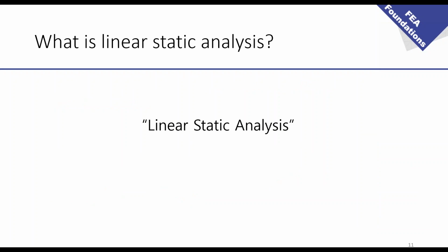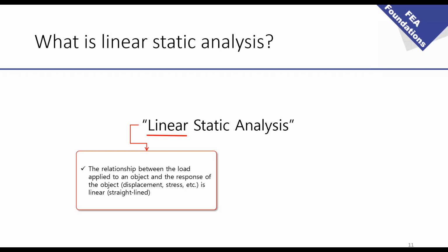What is linear static? Why is it called linear static analysis? I just took these three words, linear static analysis. Let's look at the first word, linear. It's called linear because the relationship between the load applied to an object and the response of the object, which means displacement and stress, is linear. You see I have a curve, so basically the force is proportional to the displacement. That's why it's called linear.